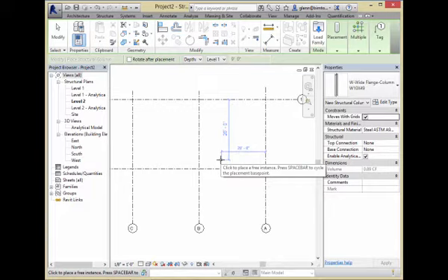In terms of placing, let me warn you about one very funny difference in the way people view the world between architects and engineers. When you talk to architects and you're placing things on level 1, they tend to be thinking about level 1 and things going up from level 1. When you talk to structural engineers and they're thinking about level 1, when they're placing columns, they're typically putting columns below level 1 to support it. Okay? And that shows up right here.